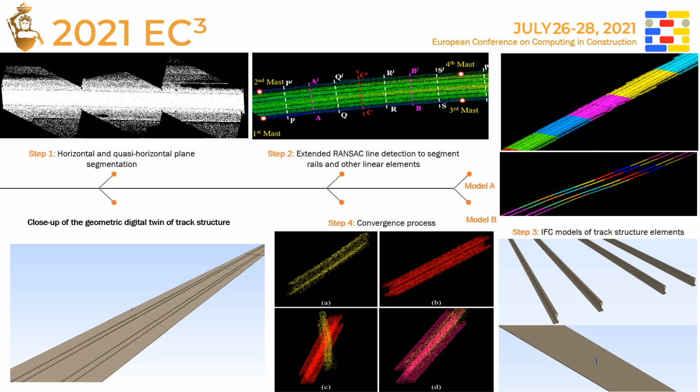For these purposes, we use RANSAC plane detection, and after this step, we assume that only linear elements on a segmented unit now represent rails, while the rest of the points on the box represent track bed points. Using RANSAC, 4 lines, which represent 4 rails in a double-track railway with maximum inliers, are then iteratively generated by determining the most probable hypothesis line for each unit.